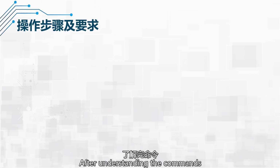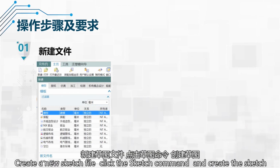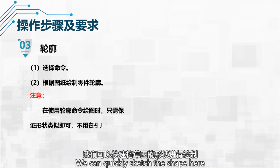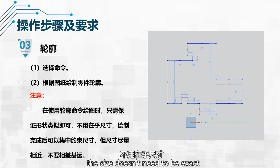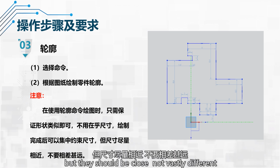After understanding the commands, we officially enter the task of sketch drawing for this lesson. Create a new sketch file, click the Sketch command, and create the sketch. We use the Profile command to draw the section of the end cap. We can quickly sketch the shape here. Note that when using the Profile command, we only need to ensure the shape is similar. The size does not need to be exact. After drawing, we can focus on constraining the dimensions, but these should be close, not vastly different.